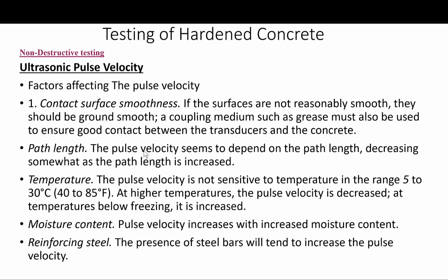Temperature. The pulse velocity is not sensitive to temperature in the range of 5 to 30 degrees Celsius. At higher temperatures, the pulse velocity is decreased. At temperatures below freezing, it's increased. Keep that in mind. Moisture content also: pulse velocity increases with increased moisture content.